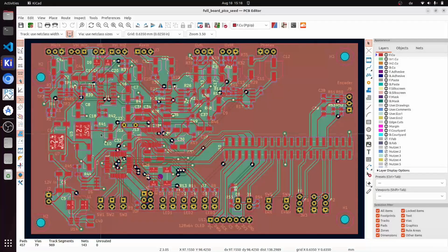By the way, the CS4270 also has the advantage of having all the analog connectors on one side and all the digital on the other, and so this made it pretty easy to design it like this, or at least not too difficult. And power supply is more or less on the left part, situated here. Digital power supply is at the bottom here, just to again try to separate it as much as possible.